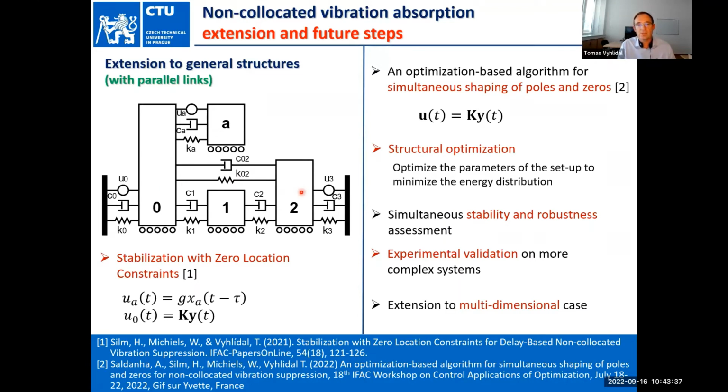So the structure is not fully serial. We have some parallel link, so it means that the resonating substructure cannot be defined so easily or directly, and the synthesis is performed by directly placing the zero position on the imaginary axis.